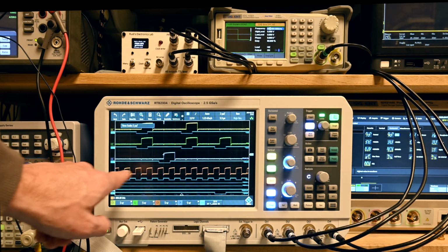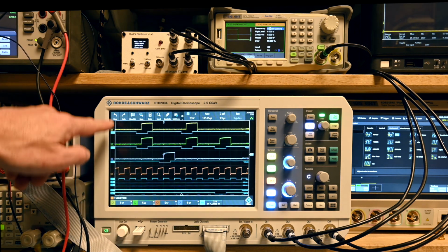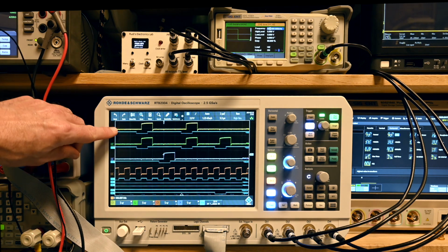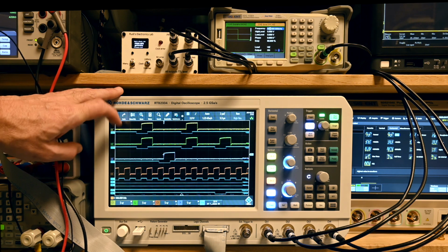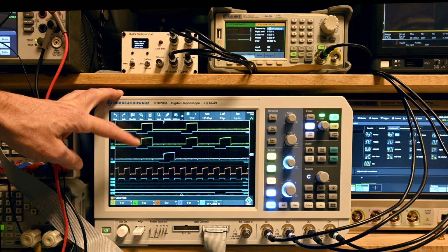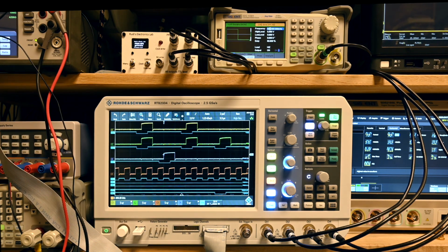And this is not happening for the digital signal of the clock. And this totally makes sense. This is why we have the hardware circuit for correcting jitter, because what we see here actually is the jitter of the Arduino, the Teensy. And that timing is properly corrected by the circuit with the flip-flops here. So the flip-flops have a super steady timing that runs exactly in sync with the clock.